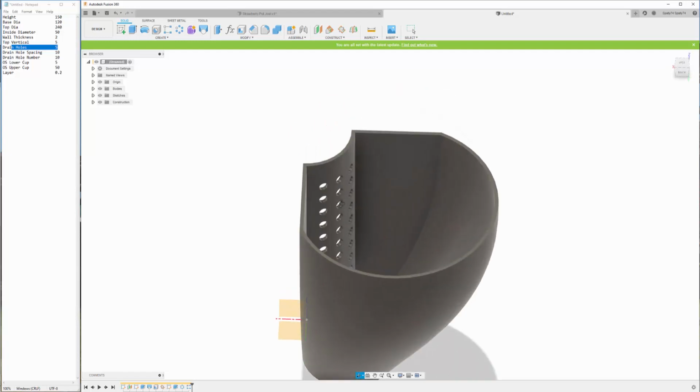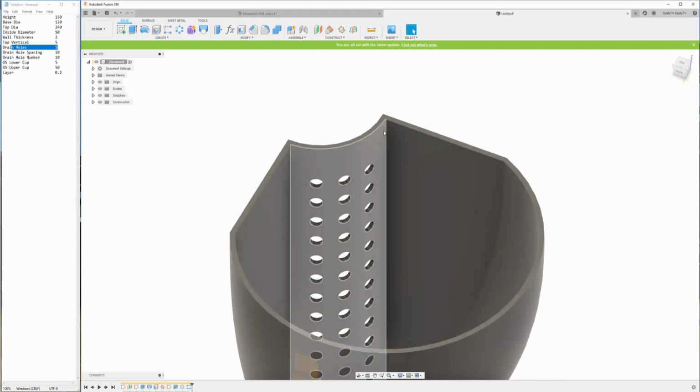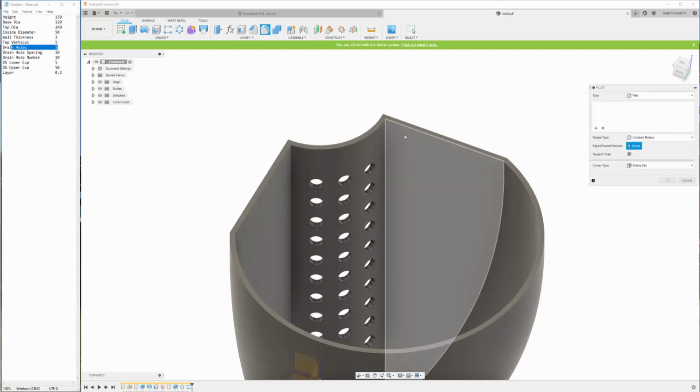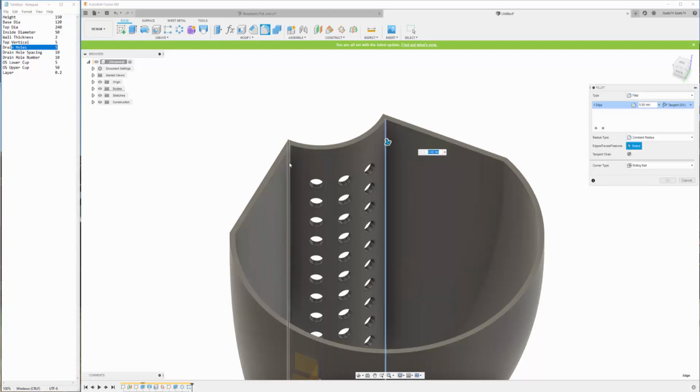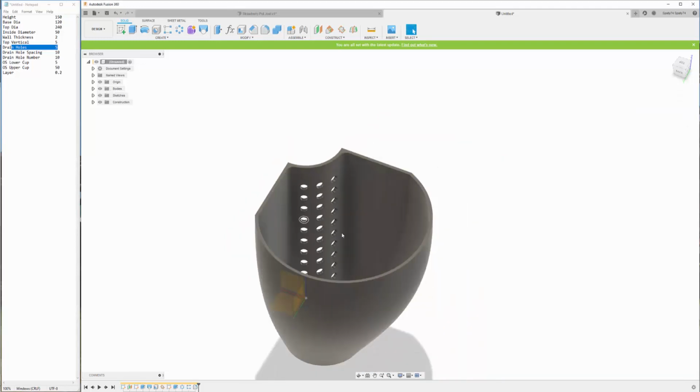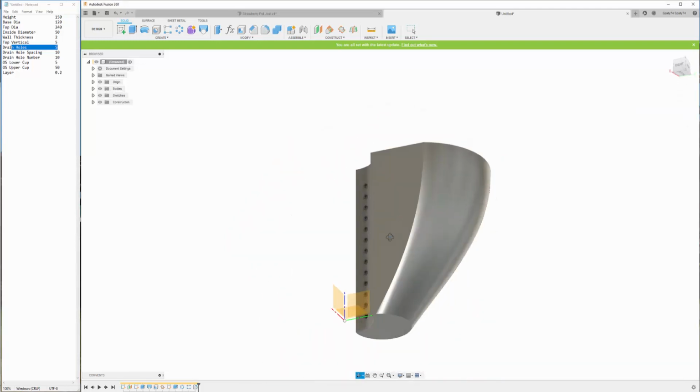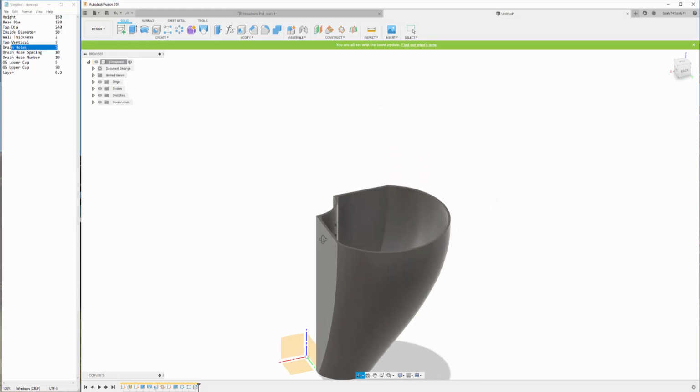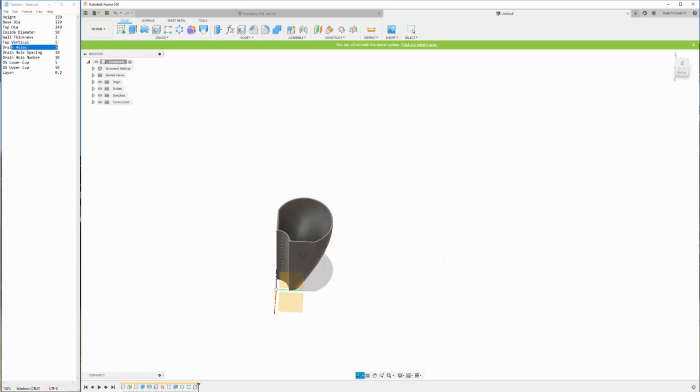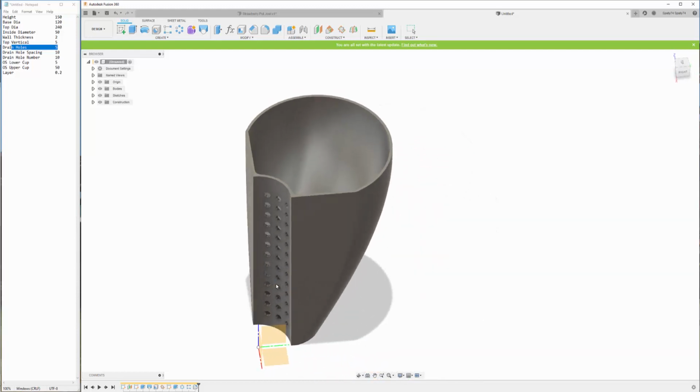Once again, thanks to Angus, corners create cracks. So what we'll do is we will fillet it here and here, and we'll give that a 5mm radius. So now we have our dynamic flower pot or strawberry pot. So once again, I'll do my rotational pattern. This time I'm going to select bodies.